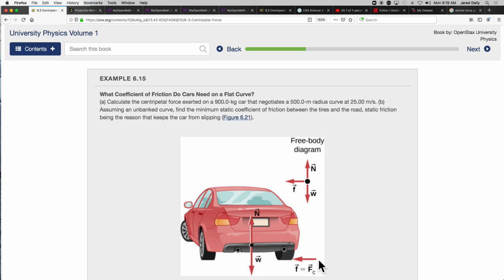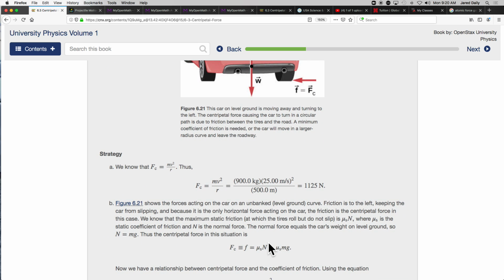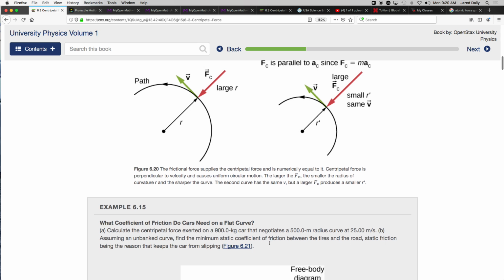So for the sideways force on the tires, there's no sliding going on there, unless you skid. If you skid, then it's a different thing. But if you turn without sliding, then you're fine. So in this direction, the tires technically aren't moving left and right. They're just turning left and right, and that turning causes the friction, which pushes the car. So it is static friction.